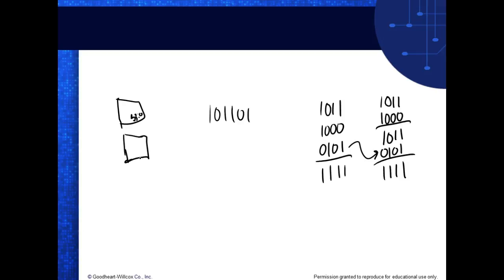So we need to have the ability to do that with an instruction. But if we do contacts, we're only working on 1 bit at a time, right? You understand? When we do these ANDs and ORs and NANDs and NORs, we're working on words. So I could come in, I could load in a 16-bit input port and OR it with something, or AND it with something, or exclusive OR it with something, and then use those results to make a decision.